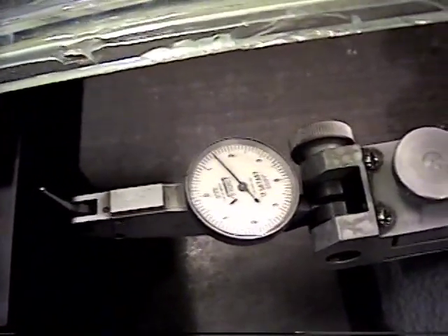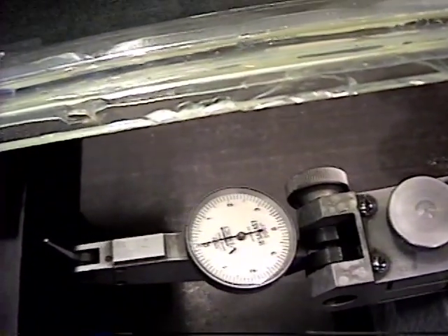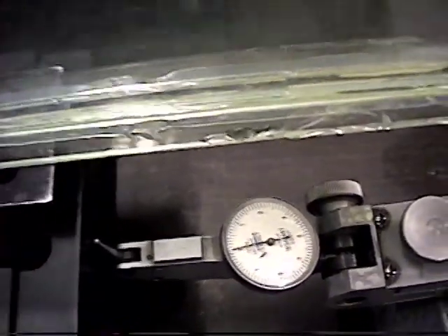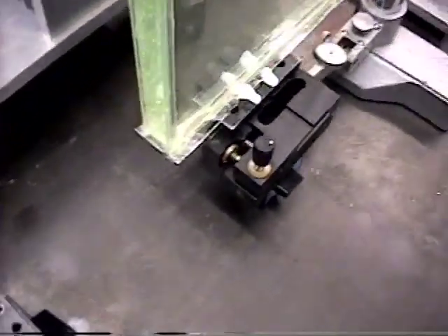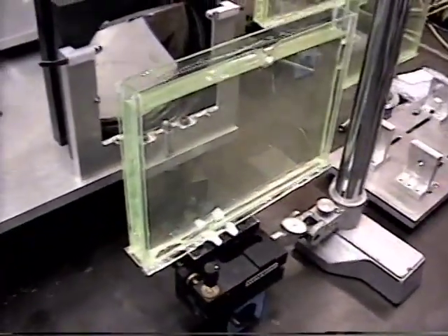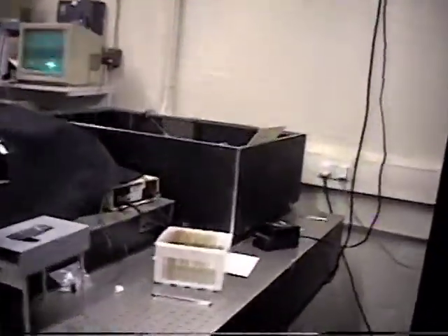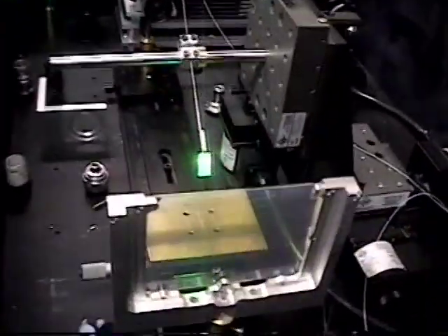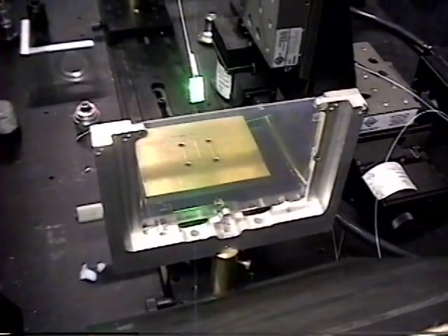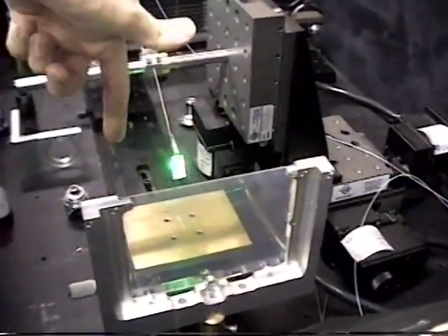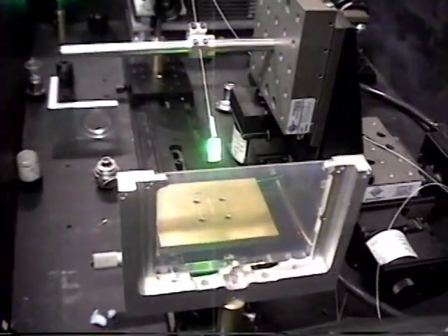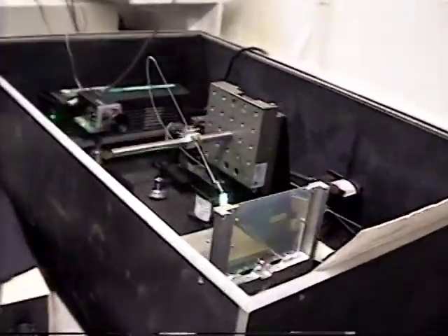Very simple: as I adjust the stage, I can then rotate the dial. The needle of the dial gauge follows the displacement of the stage. And this seems to work very well. I made a hologram of this, and today we are analyzing this hologram. We are going to make a plot as a function of linear position along, parallel to, the hologram. We'll make a plot of the displacement at each position, and that's what we're after next.